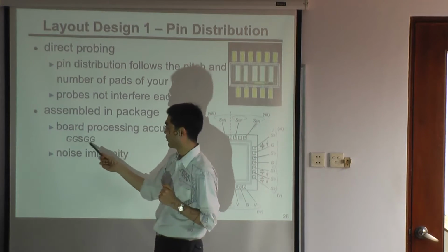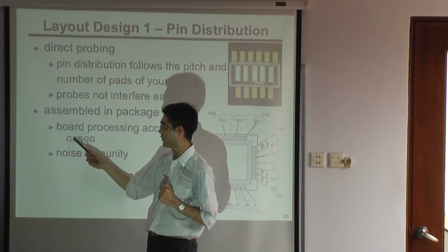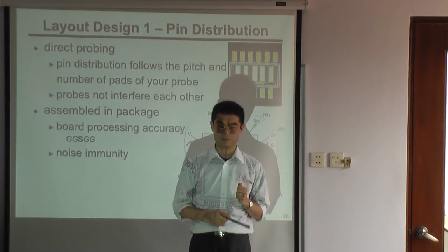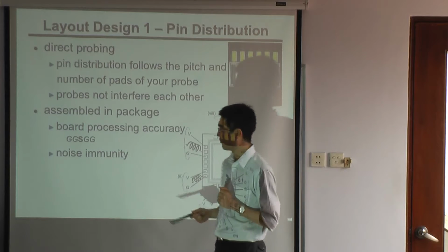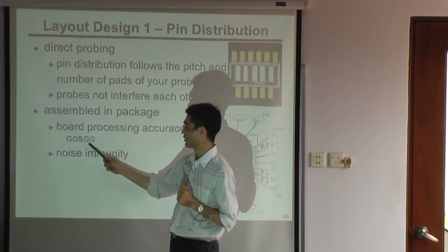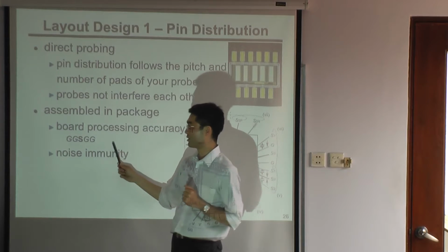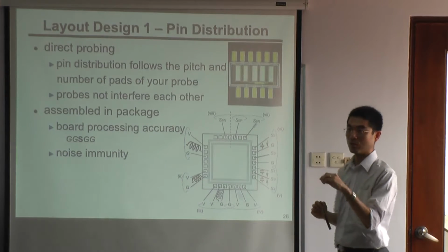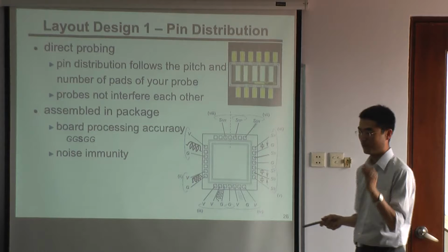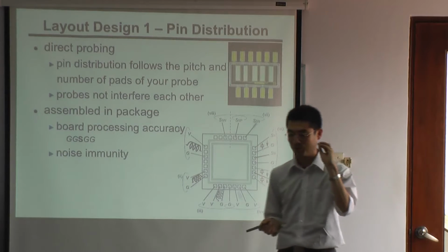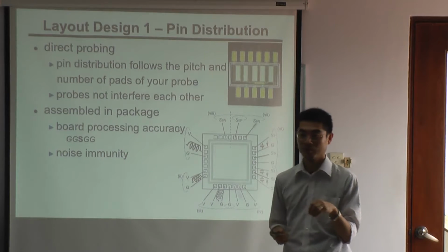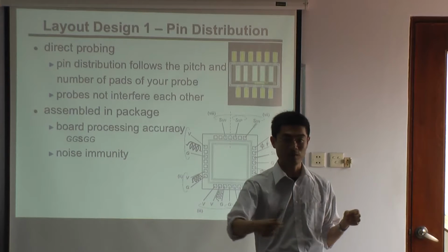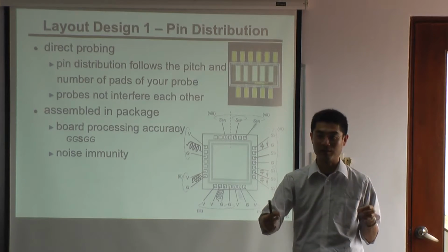I often use signals sandwiched by 2 grounds: GSG, VGG, SGG, so that it is easy to work on. Sometimes you have to put chip capacitors, or sometimes you have to connect 50 ohm transmission lines.